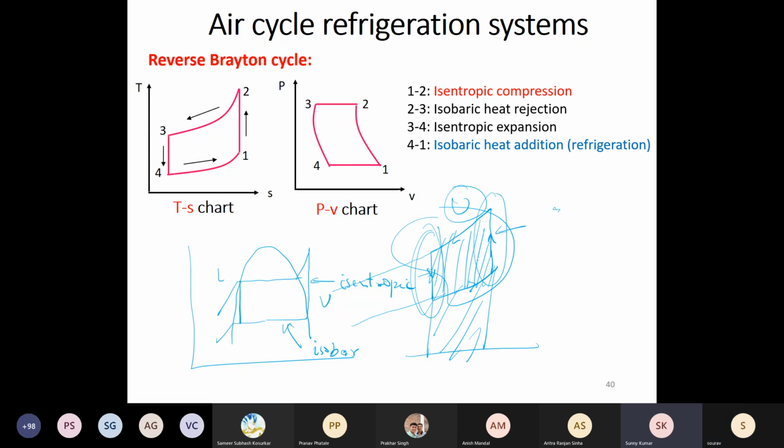The logic remains that now in this case, the amount of power generated here would be a significant fraction of the amount that we have to provide in the compressor. Okay, it could be of the order of 30 to 40%.